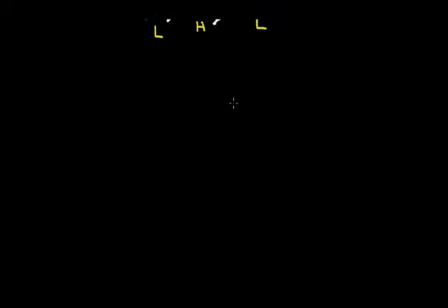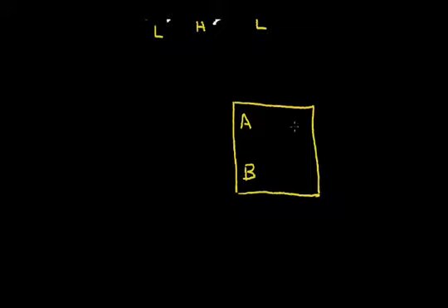And let's sketch the symbol for a multiplexer. So the multiplexer has two inputs, A input and a B input. It has an output, and it has a select signal. Let's call it select A. So again, if select A is at high condition, the A signal, whatever is at this node, is transferred to the output. If select A is in a low state, it sends the B signal, sends this node over to the output.